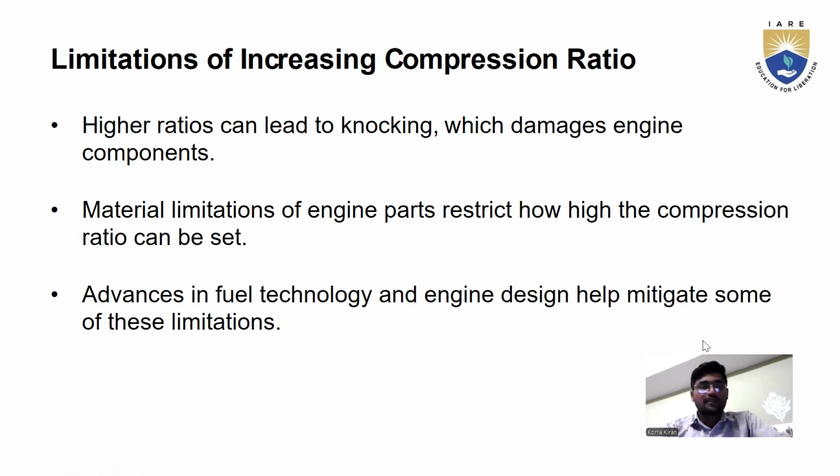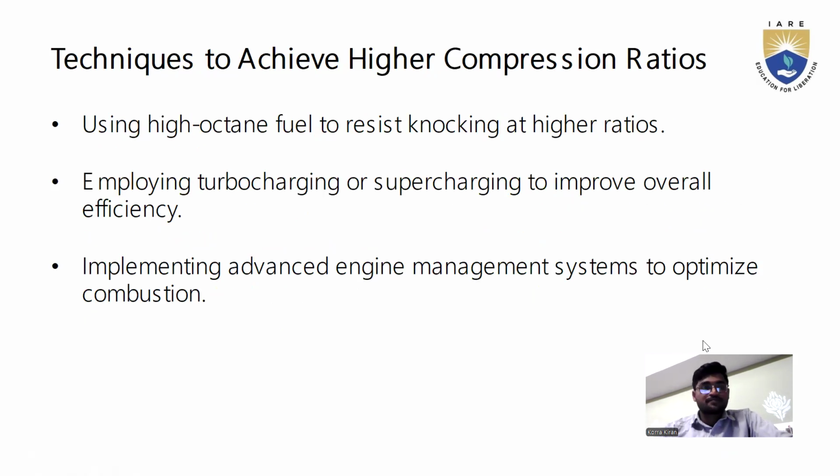Now we can see the limitations of increasing compression ratio. A higher ratio can lead to knocking, which can damage engine components. Material limitations of engine parts restrict how high the compression ratio can be set. Advances in fuel technology and engine design help mitigate some of these limitations.